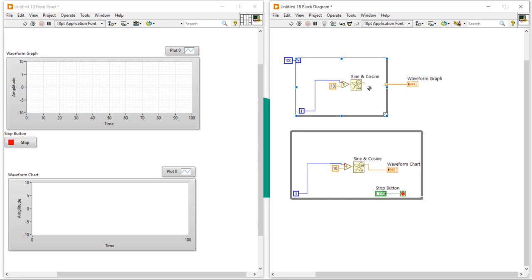If we put the waveform chart, we can also display all these values, but we cannot connect a waveform graph with this single value. Whenever the loop runs, whatever data it generates, each and every data point we can display using the waveform chart at runtime, in the current time, during data streaming. So now let's press Control H.